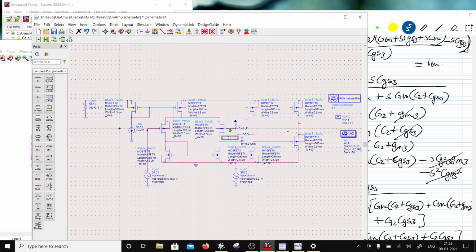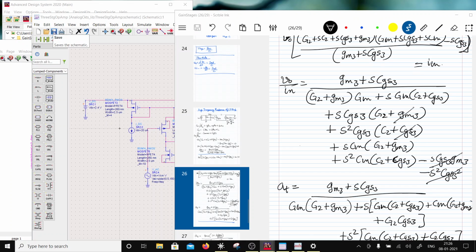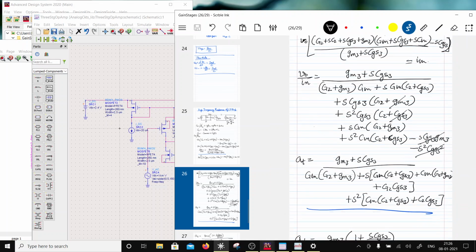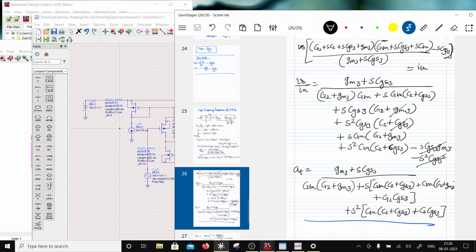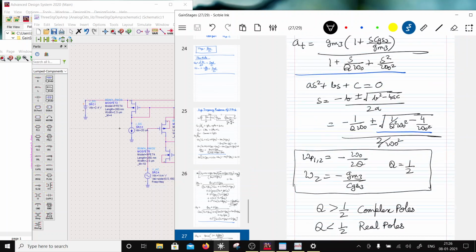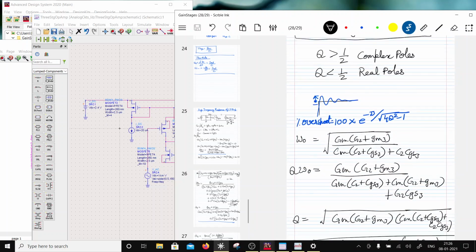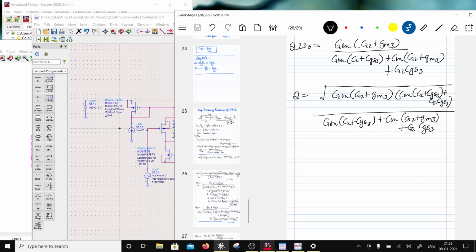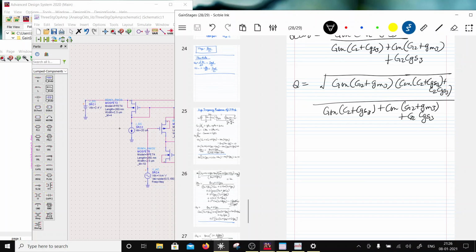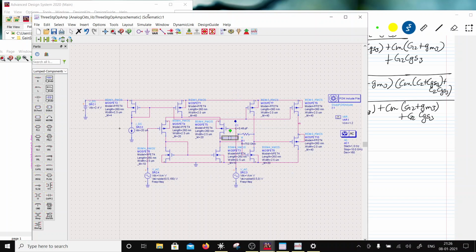So I might not need further frequency compensation on this, but I am not going to derive this because you can find n number of books which derive it, right? All the point is that you have to sufficiently load the gate node or the input node with R and C to ground so as to stabilize a common drain amplifier.